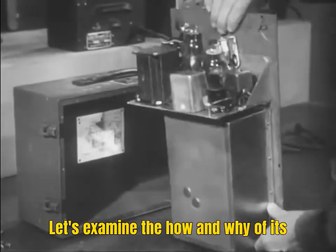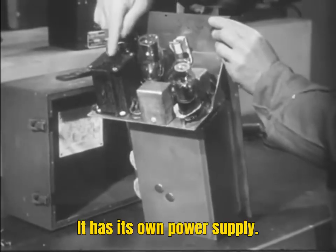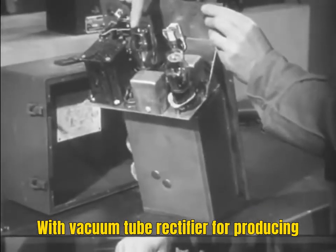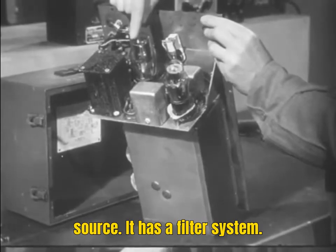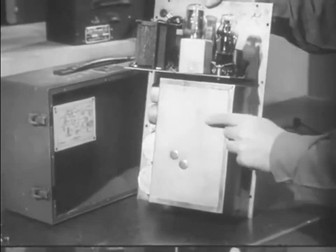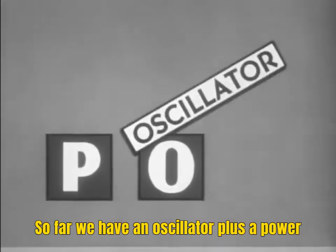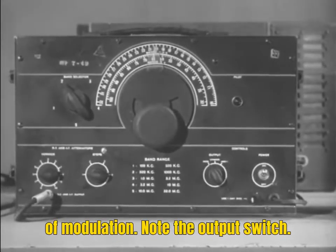Let's examine the how and why of its operation. It has its own power supply with vacuum tube rectifier for producing DC voltage from a 110-volt AC power source. It has a filter system. And, of course, a vacuum tube oscillator. So far, we have an oscillator plus a power supply. Next, for an explanation of modulation.